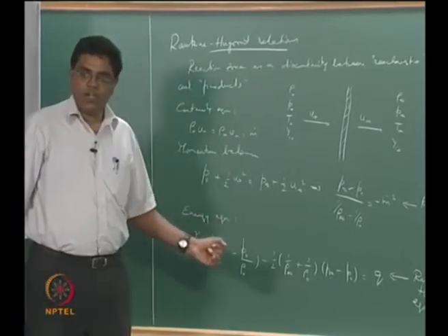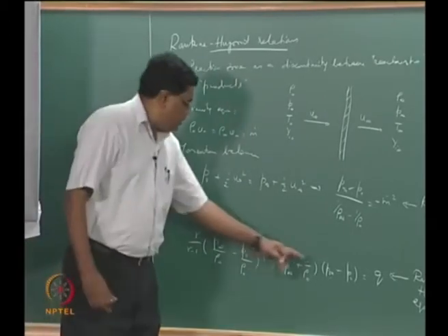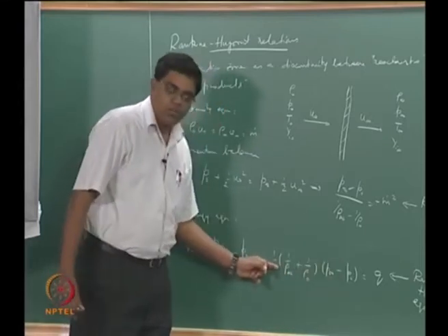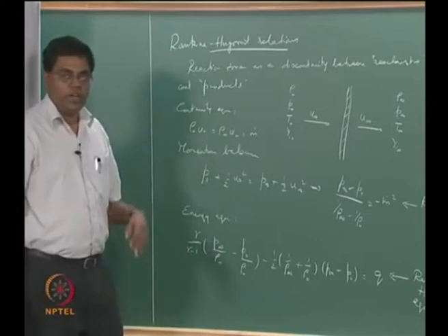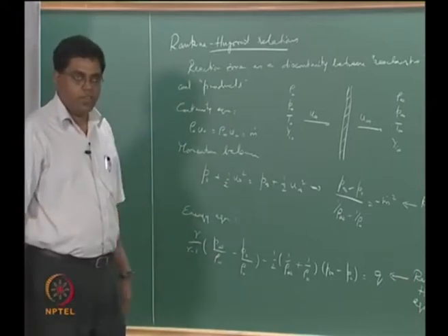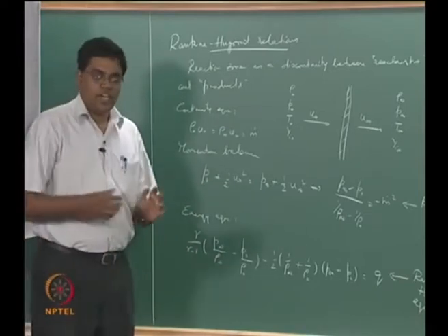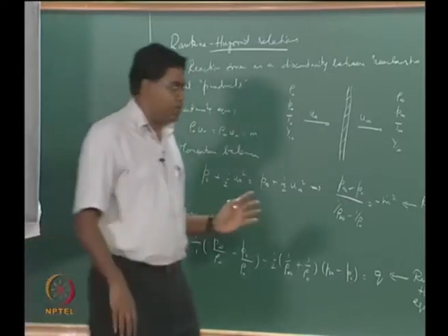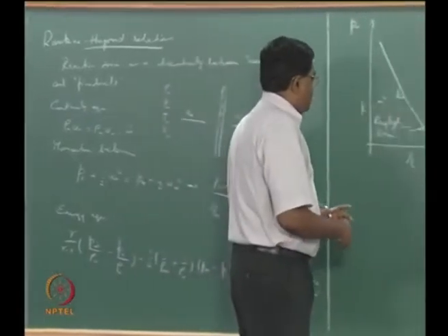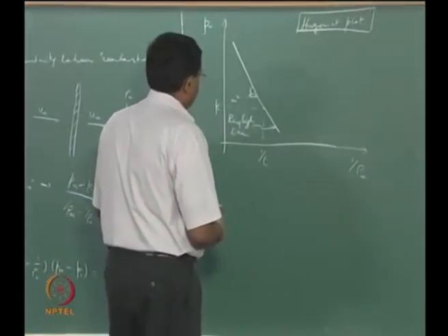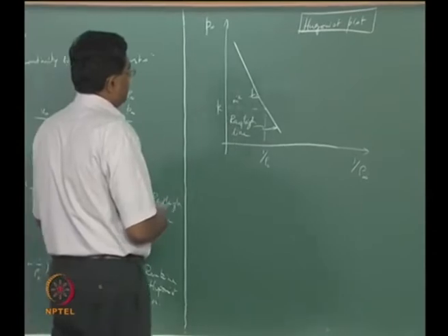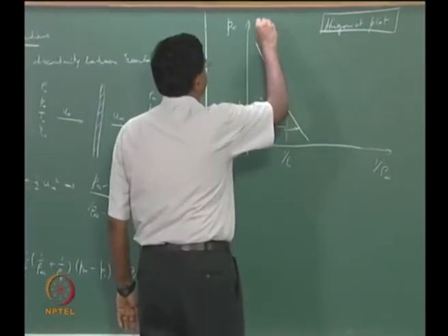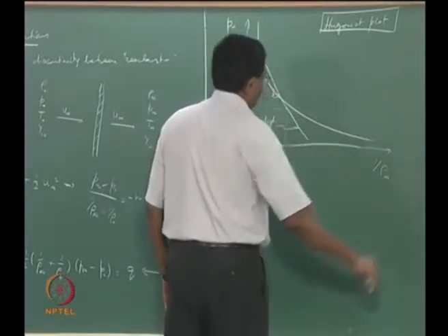But since you also have a P infinity divided by rho naught term and a P naught divided by rho infinity term, we have some b's and c's that are non-zero. Therefore it's not exactly a rectangular hyperbola, but modified, so it is going to be a hyperbola that looks something like that.